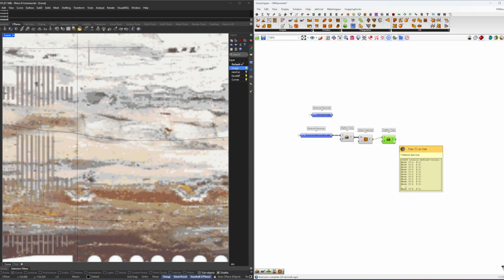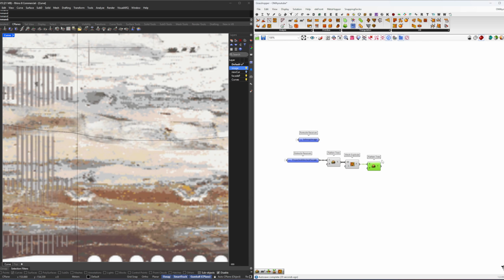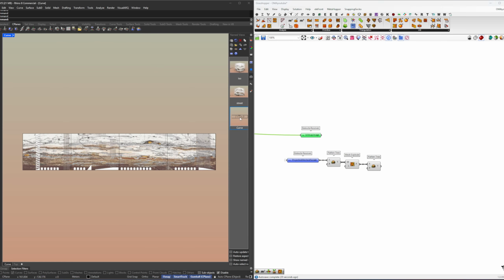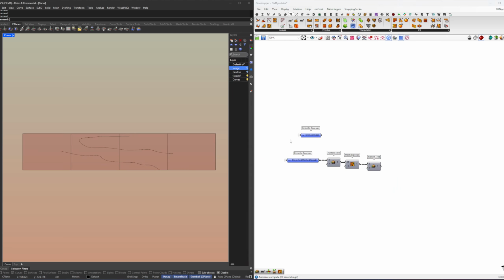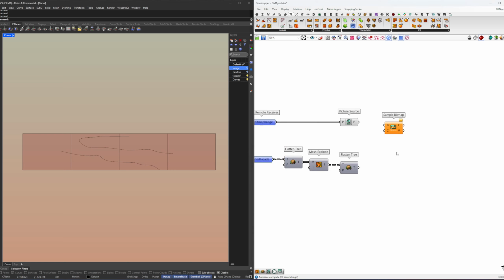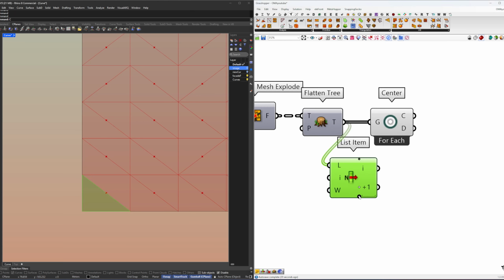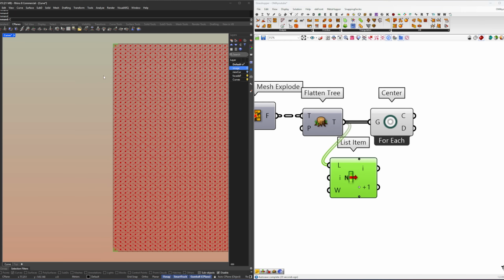So we have like 2400 indeed. Let's zoom a little bit out here, and maybe also hide the image for now. So our bitmap image. First we need to get the picture source, because then Grasshopper can read the picture source. And then we need sample bitmap. So this is the path of the source. Because here we just have like 1 and 2.